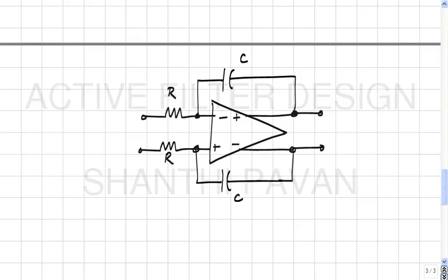okay. Now if this was VCM plus VI and this is VCM minus VI, then all that the op amp is enforcing is that through negative feedback eventually the difference between these two nodes is 0. It does not say anything about the absolute value of these two nodes. Okay. So which means that the differential current flowing like this, right, will be Vi by R, this will be Vi by R, with output common mode voltage is forced to VCM using a common mode feedback loop, okay, as usual.